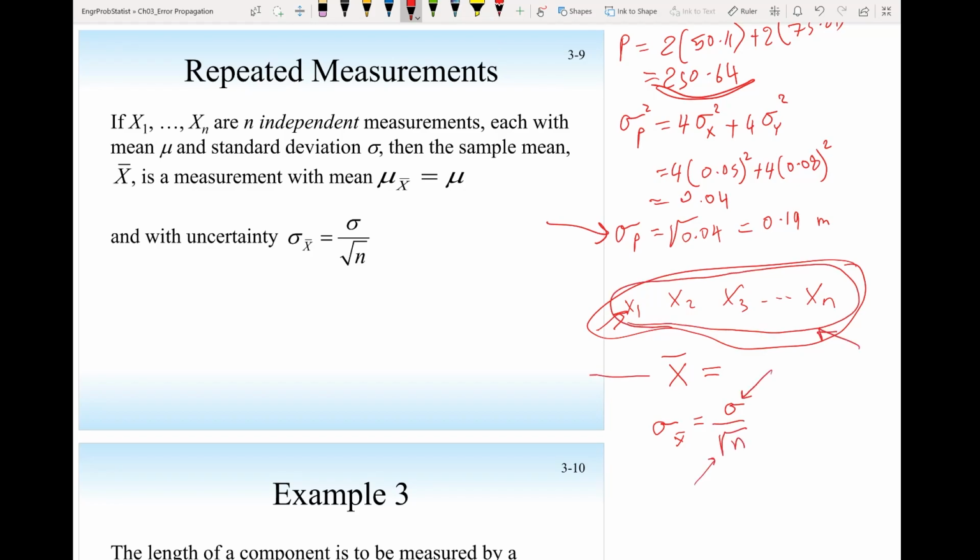So when I say the average amplification of this op-amp is 10 plus minus this quantity, I would be more precise. That's why when you make measurements, make sure you take at least 5 to 6 measurements to estimate the parameter you are measuring with more precision.